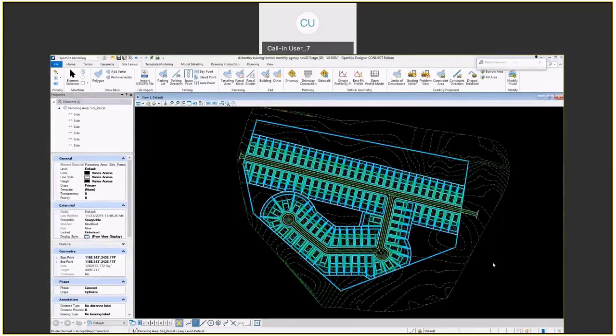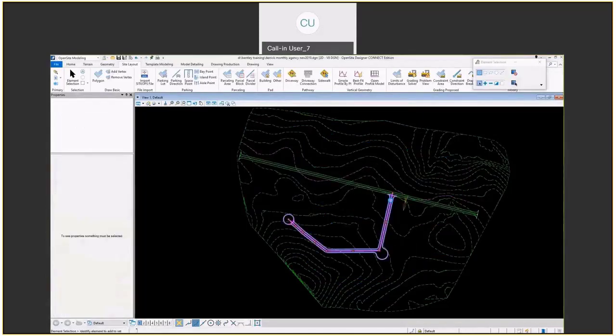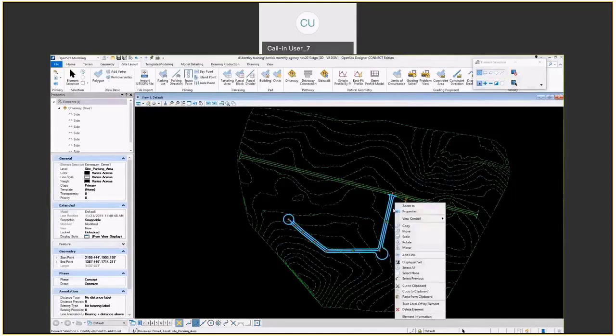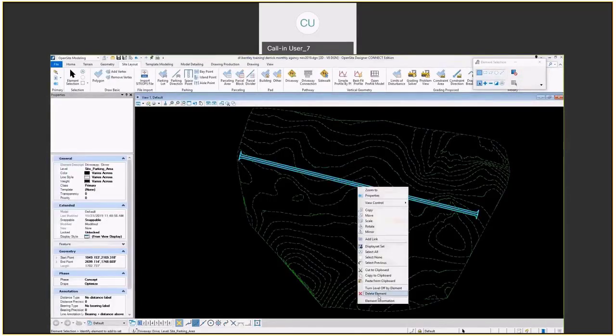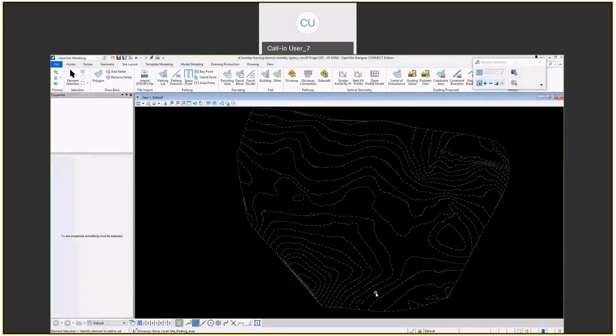A parcel block is nothing more than a parcel area, and I want to break it up. So if you think about it, we're doing right-of-way takes, and we get a bunch of shape files. I can bring those in, turn those into parcels, and as we start acquiring property because of the right-of-way, or we're adding to something, we're moving it, and as we're constantly changing the road design, you can change that right-of-way line or easement line or whatever you want to call it as breaking the parcel, and it will give you separate parcels. So to do this, we just draw a block area.